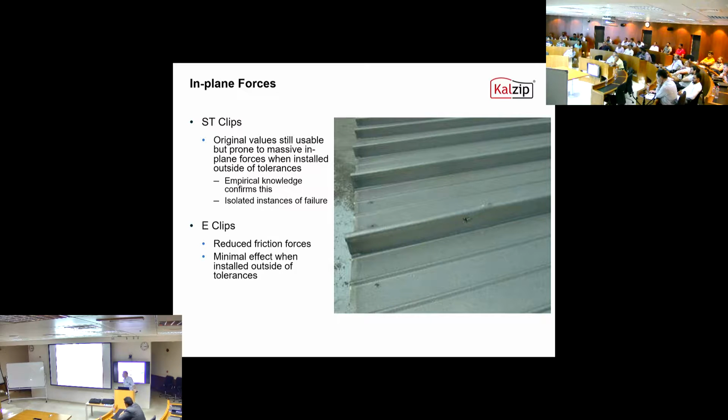How would it be solved? Luckily, we were able to examine it: we unzipped the sheets and lifted them out of the way to see what the problem was. In this instance, the fastener hadn't been installed correctly, so we were able to replace the clip. We do a small weld over that area, put in a new clip and new fasteners, and the problem's solved.